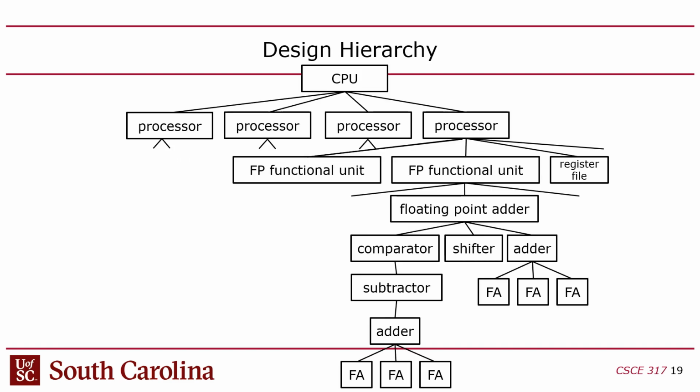So we talked about the design hierarchy where you have modules instantiated inside of other modules, and we also talked about this idea of regularity where you try to design modules that can be used repeatedly, like an array, right? And this is the way that chips become 10 billion transistors. It's not because someone actually wired up 10 billion transistors, because that's impossible.